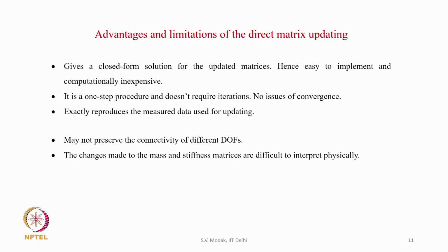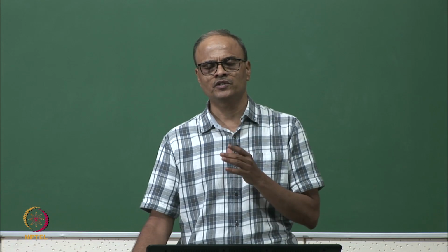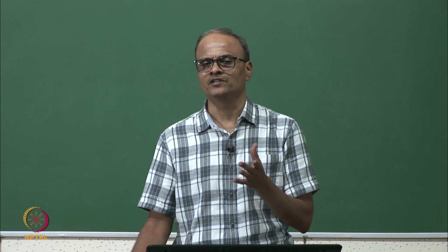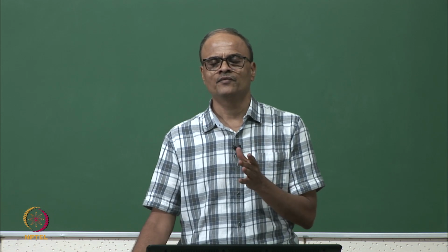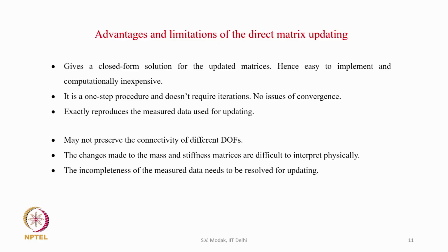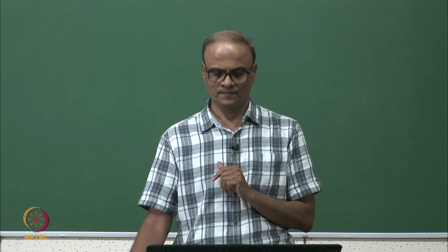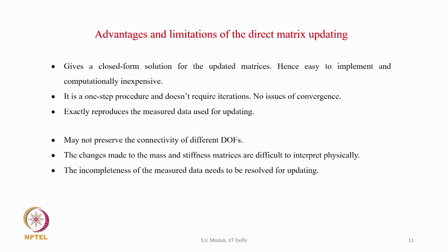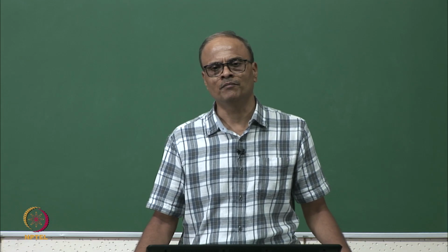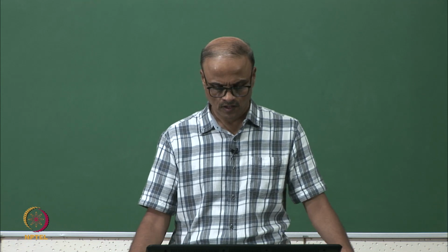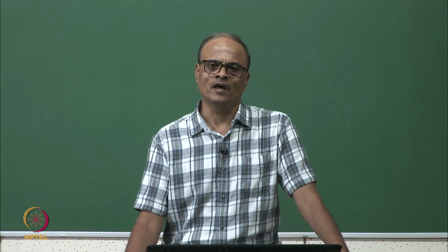Also, the changes made to the mass and stiffness matrices cannot be interpreted physically. It is difficult to attach any interpretation to those changes, as to the reasons for which these changes have been made in the initial FE model. Also, because the measured data is incomplete, these methods require that the incompleteness issue be resolved first before updating can be done. Therefore, either model reduction or mode shape expansion needs to be carried out to implement these direct matrix updating methods. So, these are the advantages and limitations of direct matrix updating.